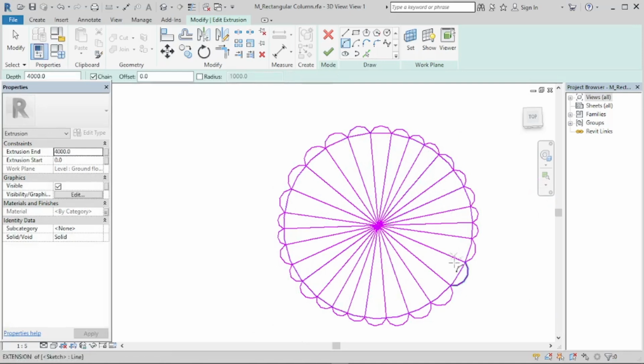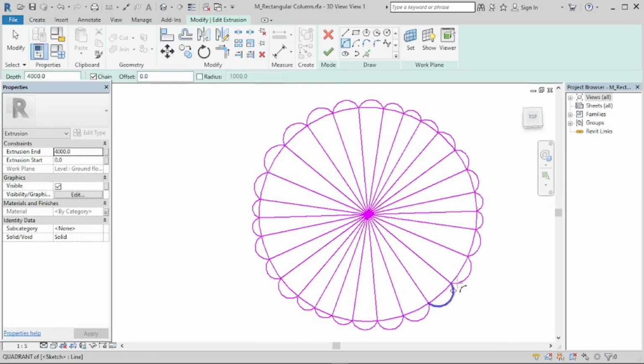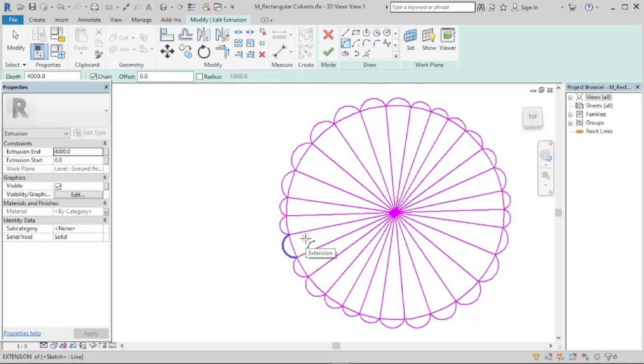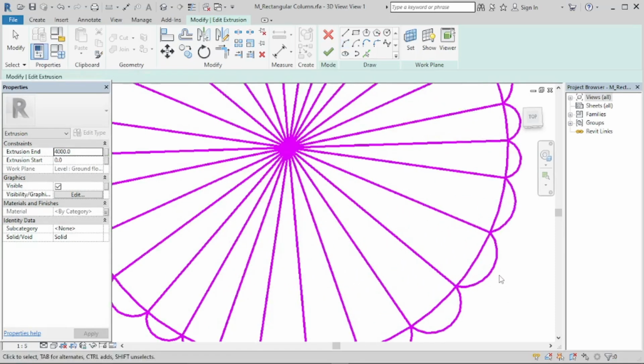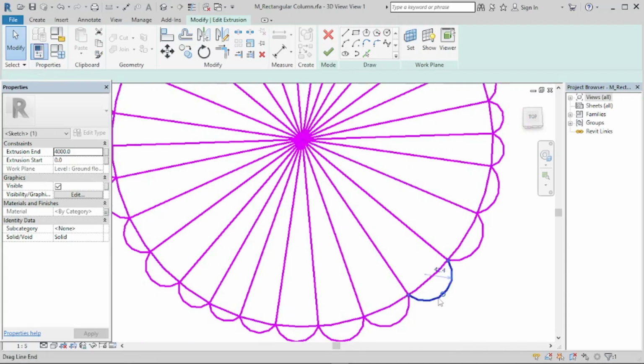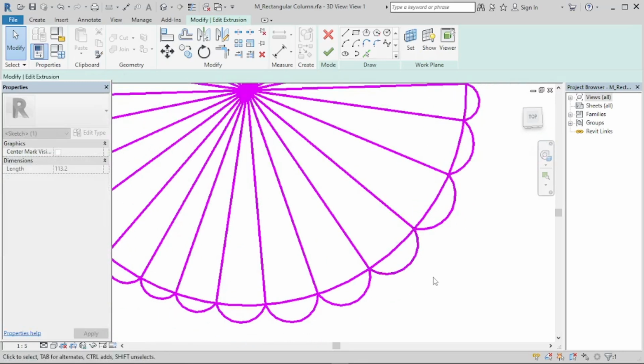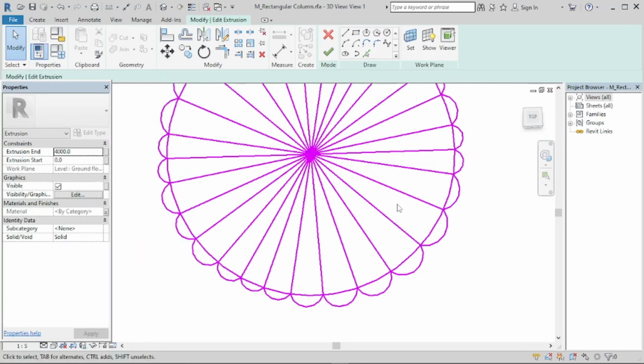we've got all these arcs around, but if you notice, some are wider and some are smaller, some taller, and all that. So let's see what we can do about that. For this particular one, let's see if we can control that. Okay, we can actually control that by doing another thing. You can control that by, let's try to offset probably around 100 millimeters from this circumference. No, 100 is too much. Let's try 50 millimeters.